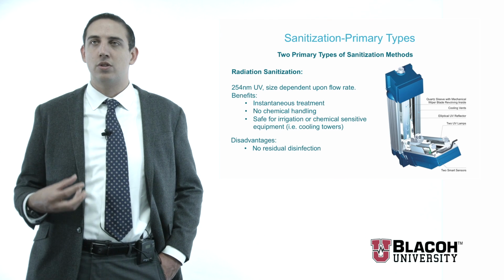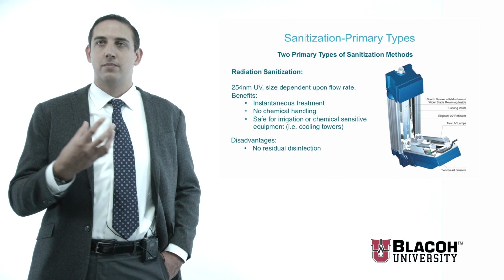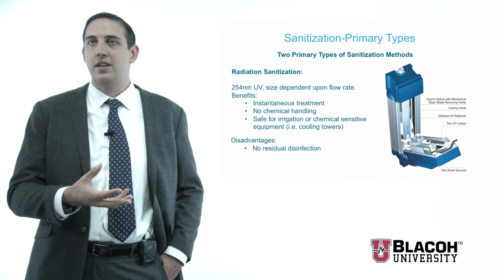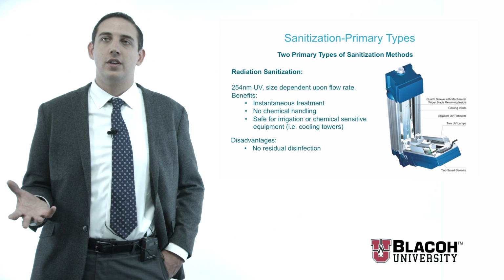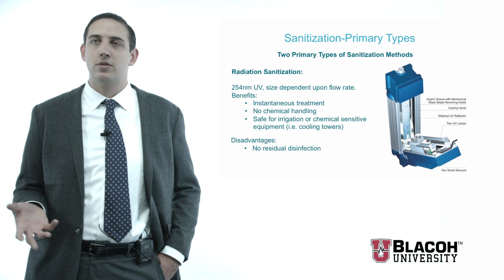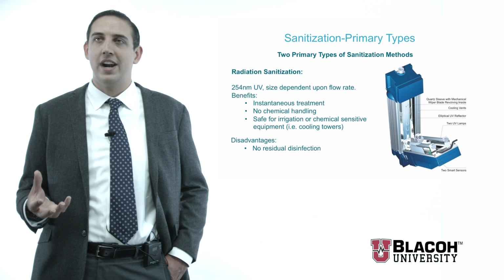And there's really two schools of thoughts on disinfection. The first is to use UV or radiation sanitization, and the second is chemical sanitization. I personally prefer UV sanitization. What you do is you basically use ultraviolet radiation. It's in the UVC range, which is 254 nanometer UV.